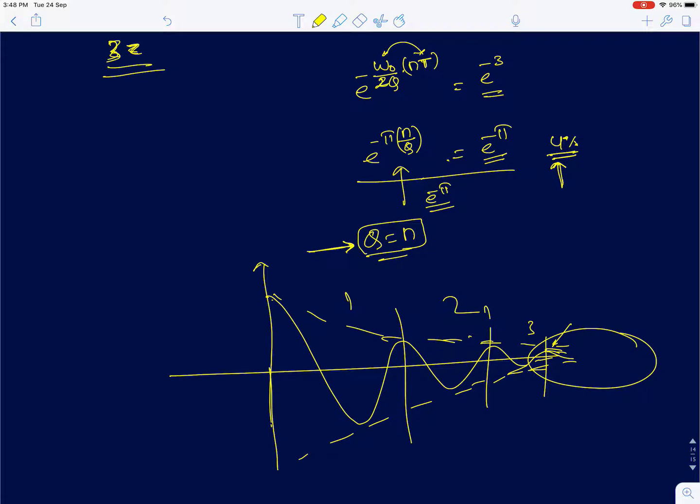But when you are seeing the whole waveform together, if the initial amplitude is large enough, you can easily count the number of visible cycles. That will also approximately be equal to Q. But to be exact, you have to start from the initial value and see when the peak value becomes 4% of its initial value. At that point, approximately that number of cycles will be equal to Q.